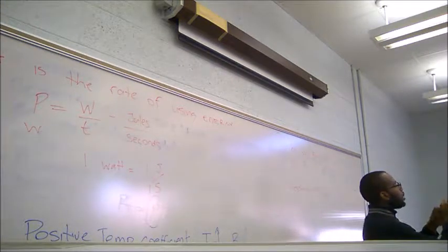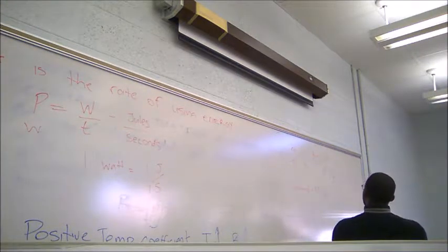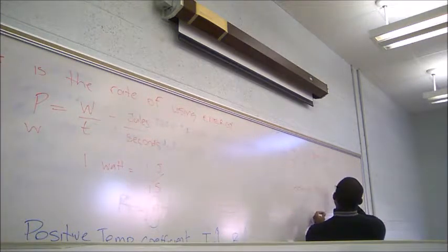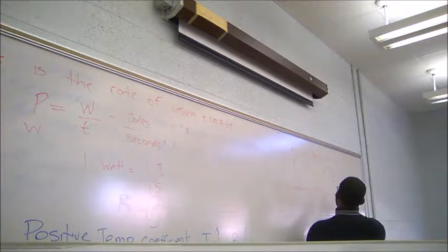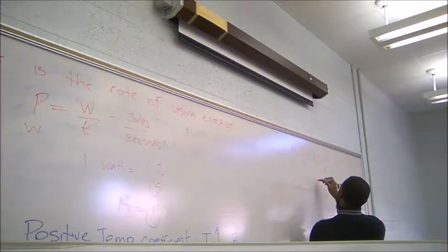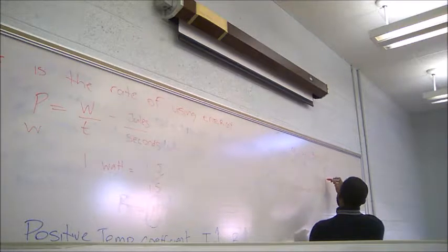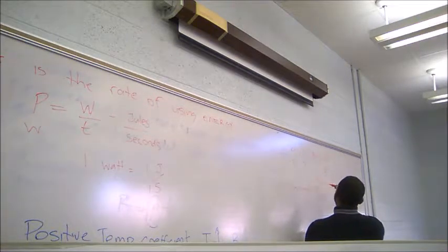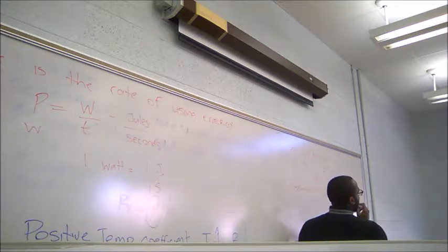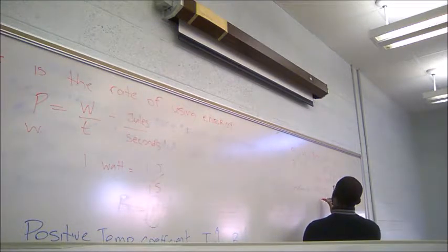Again, look, I'm going to do the calculation for tolerance. Please pay attention, you'll have to do this yourself. Okay, so based on this being 5%, the actual range for the resistance is going to be 95%. So again, 100 minus 5% is 95%, so 0.95 times 330. And so this is on the lower side, and on the upper side it can be 105%, right? 1.05 times 330.